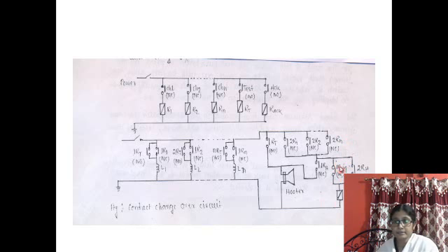Then as this is energized, then this will get closed and the path will make the circuit of RH. So RH will be energized. As RH gets energized, then what will happen? This will break. One RH is an NC type. So when it is in de-energized condition, it is in closed position.